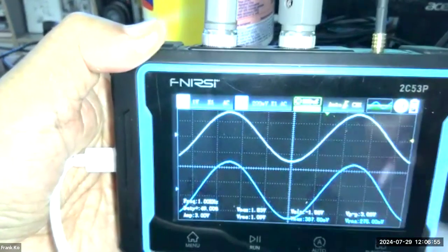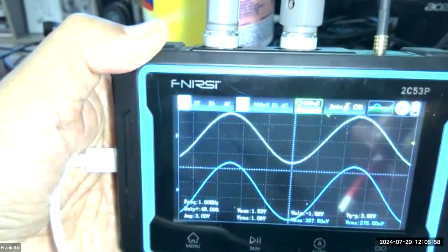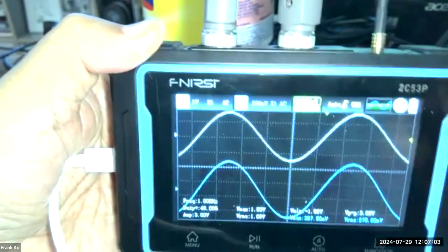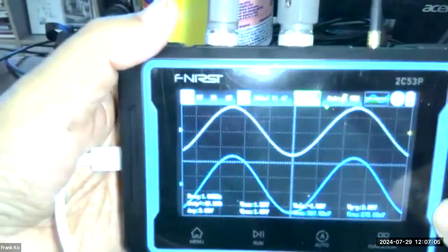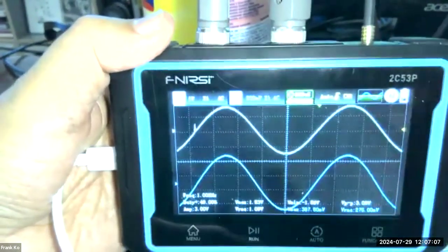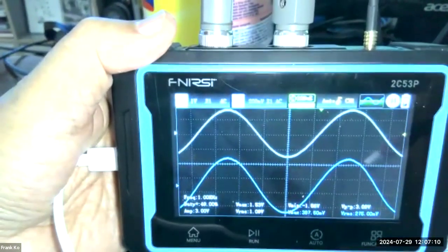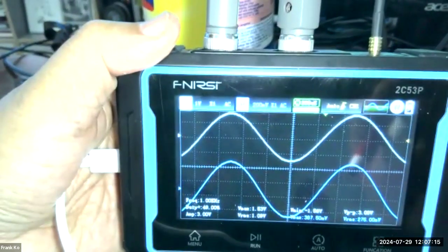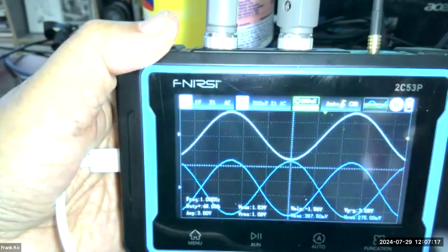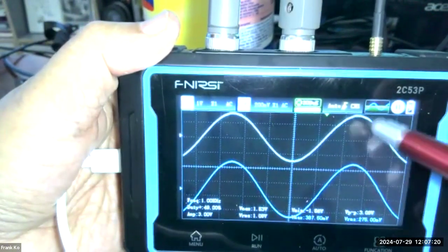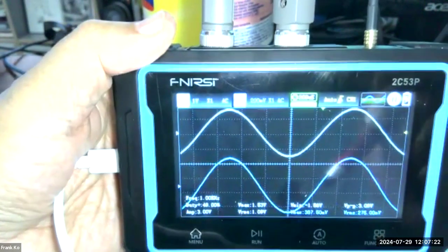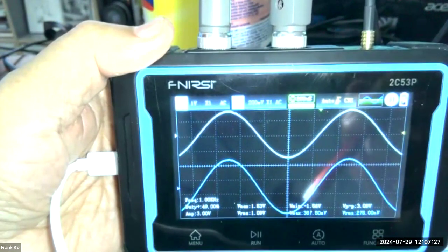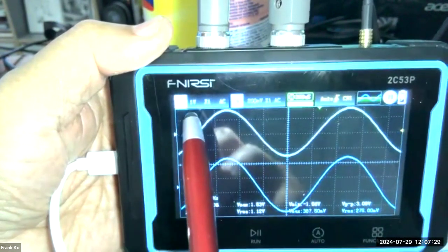And these wave shapes look to be in phase, and the wave shapes look pretty similar in size. And you know that that's not going to be the case, because your channel 2 is coming off of point C in your schematic. And point C in your schematic is one of the lowest values, should be 370 millivolts. But why is this 370 millivolt looks taller than the 1.5, 3-volt peak of the input waveform? Well, they're on two different scales.